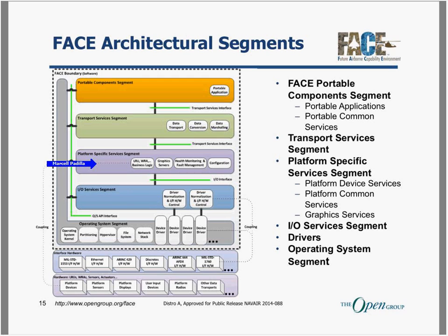So moving up the stack, the next segment that the FACE architecture defines is the platform-specific services segment. As in its title, this still has some specificity; it is not completely isolated from the outside world. I'll talk about a few sub-segments. The first one is the platform device services segment. The primary role of this is to take the sensor ICD and transform the data into a standard format that's defined by the FACE standard.